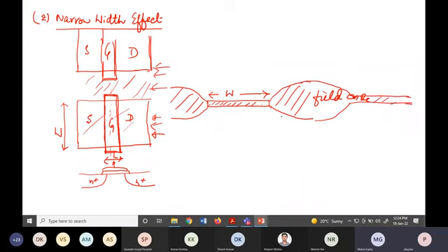So this field oxide will be very, very thick, and then this MOSFET will not be able to talk to this MOSFET, because formation of another MOSFET here is difficult, because the threshold voltage you need for that will be very, very large, right? So that is why you need thicker field oxide.